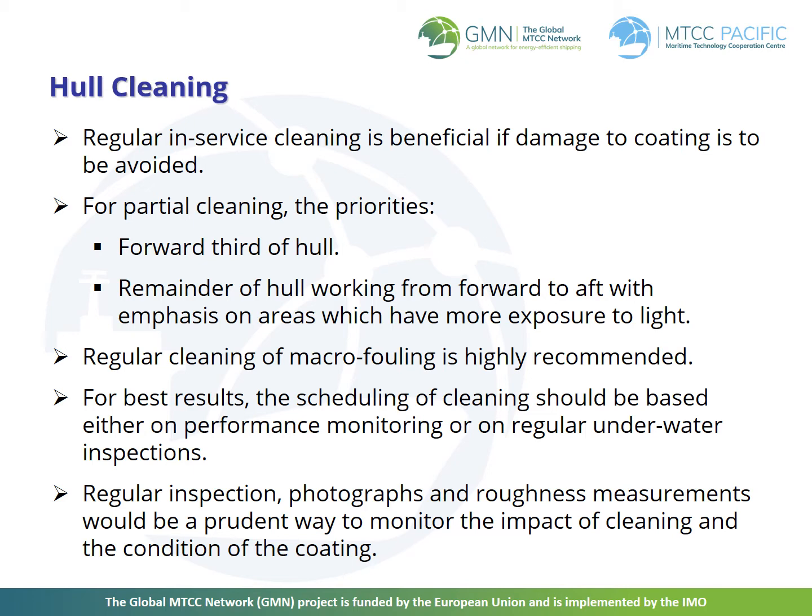Regular inspection, photographs, and roughness measurements are prudent ways to monitor the impact of cleaning and the condition of the coating. The use of underwater cleaning techniques and equipment should be done with care and with due consideration to original coating as well as to the amount of the fouling.